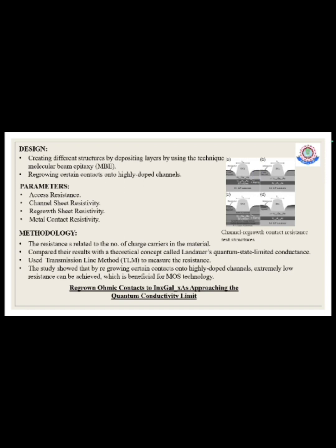By using the four samples, they analyzed how well the different samples conducted electricity and how much resistance was present at various points in the electric components. These measurements help the researchers understand the performance of the components and optimize their designs for better functionality. Finally, creating a smooth transition between the added materials and the channel material helps reduce the resistance and improve the performance of the electronic components. Additionally, they used one more heavily doped channel material, which also leads to lower resistance and better contact with the added material.